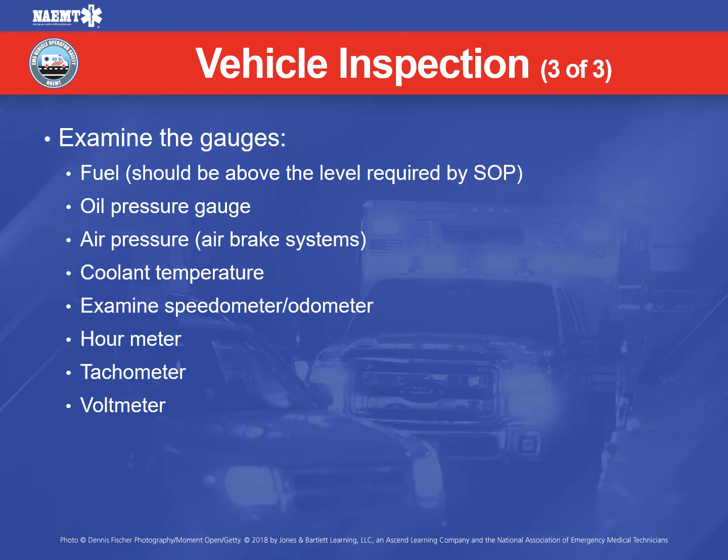I want to make a note here, class. Any warning lights that come on the dash, you need to follow your department SOPs when you're addressing them. Also, make sure you have a clear understanding of the operating manual for the unit that you've been assigned, because the operating manual will let you know what the appropriate oil pressure would be, what the appropriate coolant temperature is, and what is the appropriate amount that can register on your voltmeter.